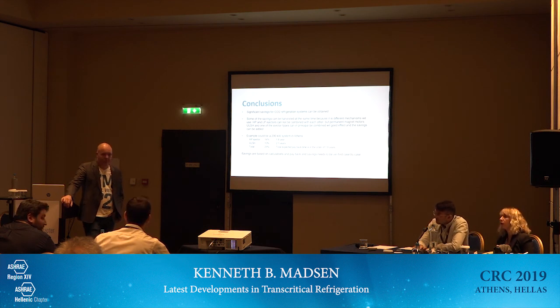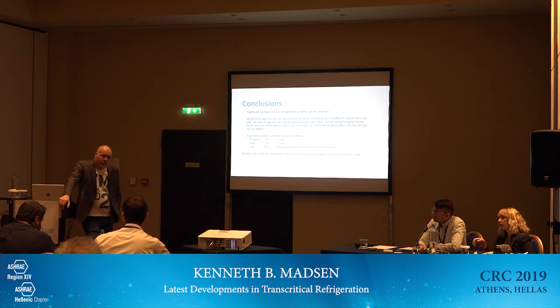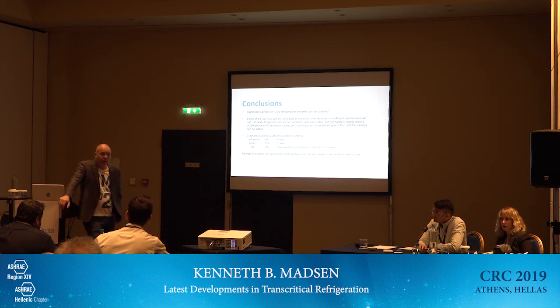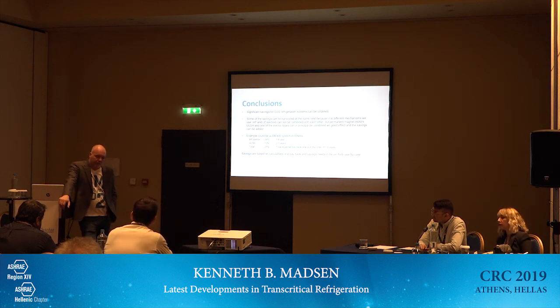And one question with low suction, low superheat: do you have any safety issues for the operators? So for example, the controller has an emergency brake. But we also have a suction accumulator, and there we measure the liquid level.